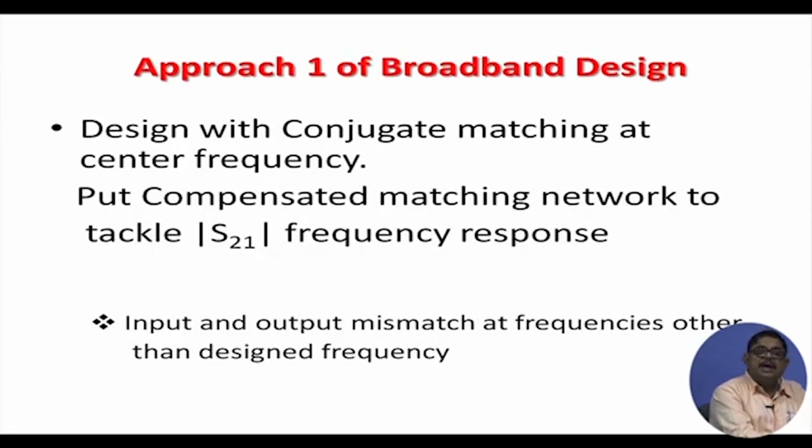So, there are various approaches. I am just letting you know what the typical approaches are. The first approach is design with conjugate matching at a particular frequency, typically the center frequency of the band in which you are trying to design the amplifier.